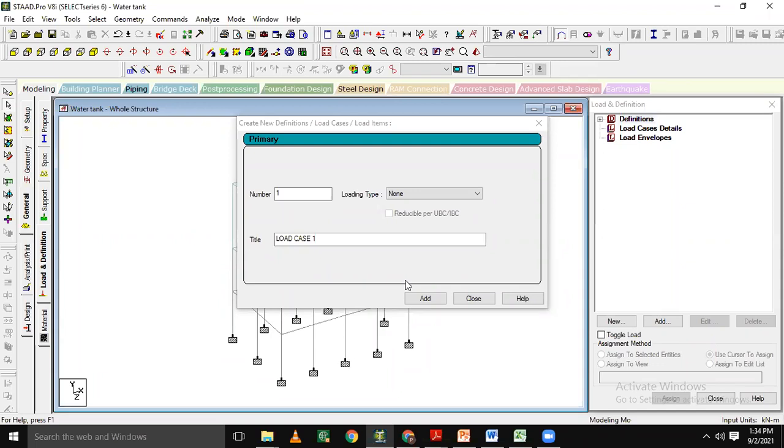Working stress method is used whenever the design needs to be more conservative. Commonly water tanks are highly vulnerable because the water level in the tank will vary, and there is highly continuous variation in the water pressure inside the tank. Working stress method fulfills the highest requirement factor and gives one of the traditional methods to account for such variation.